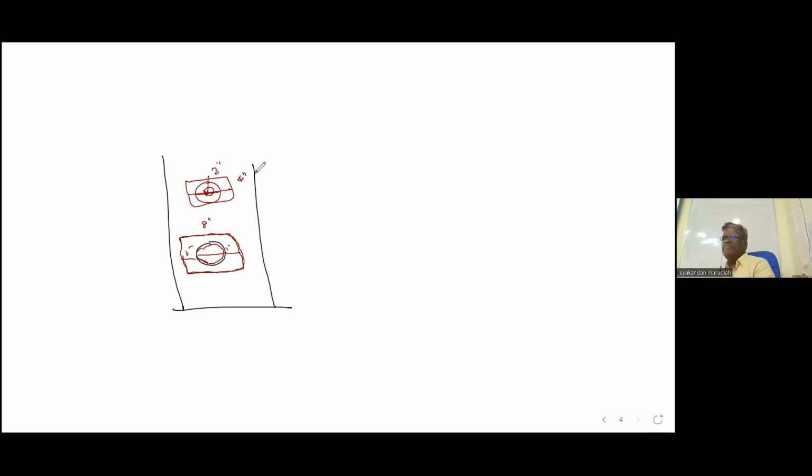Again, I will repeat. Patch plates can be used to fill a hole because of nozzle removal. The minimum size of the hole should be 2 inch. Suppose the actual nozzle removal is say 1 inch, we have to make the hole bigger, 2 inch. Minimum size of the plate will be 4 inch. 4 inch for a 2 inch hole: 1 plus 1. Okay, so see, it will be welded.